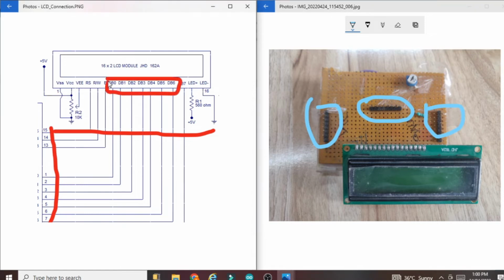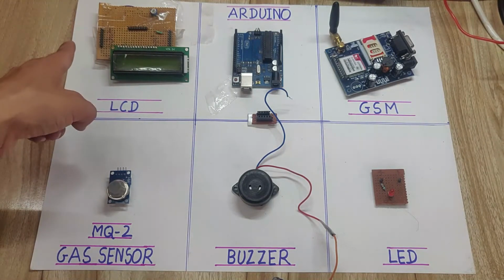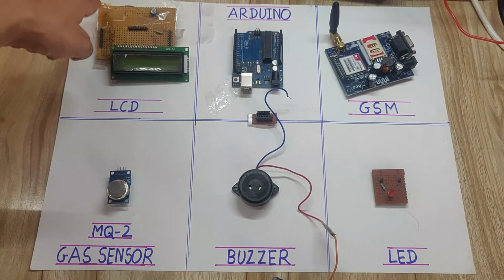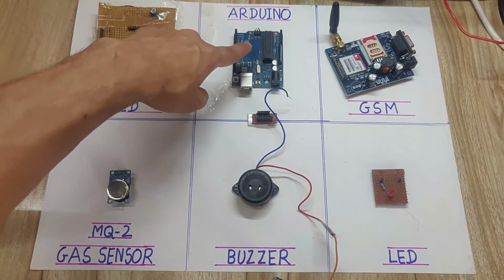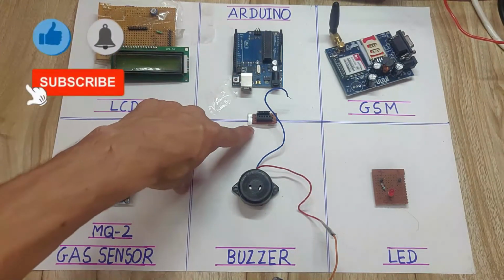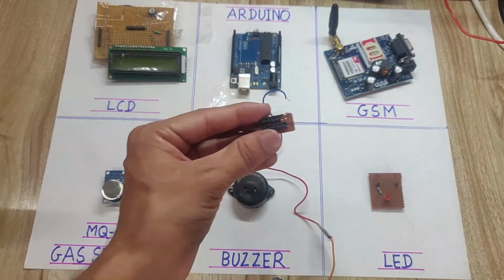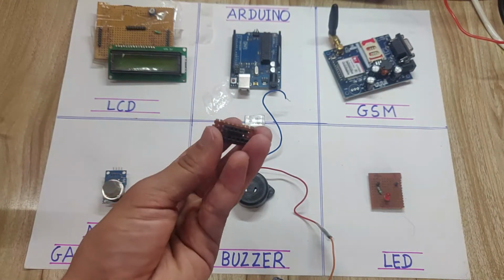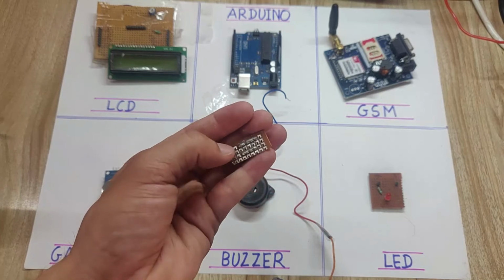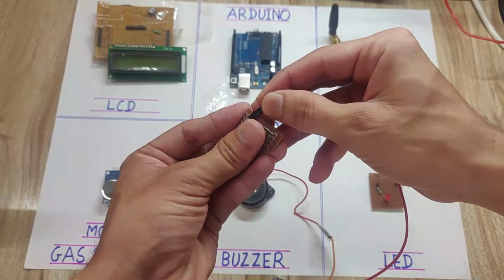So once you have created that circuit using a zero PCB or a breadboard, then you have to connect VCC to common VCC. First we take the common VCC and common ground from the Arduino to this point. So basically this is a zero PCB again, and on this zero PCB there is a buck strip. You can also use a breadboard for this, and I have connected one common buck strip as a common one. This one row is commonly shorted.